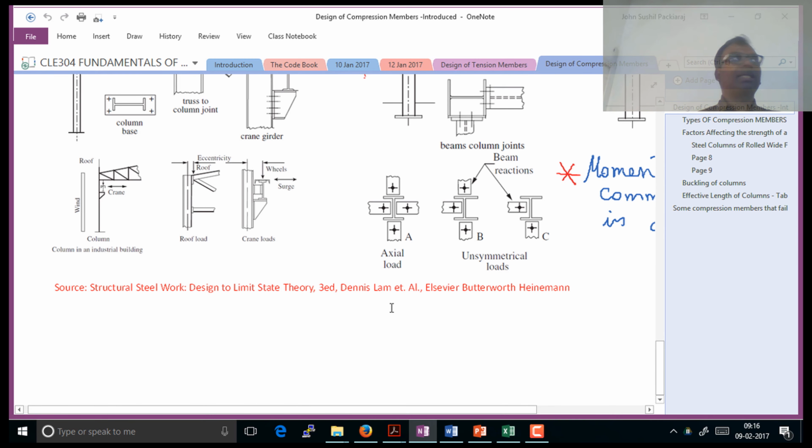If you take a typical building frame, you will have a combination of an interior column. Here this is an interior column which is predominantly axially loaded. If you have a column somewhere in the middle of the building, you got a cross beam which runs across the length like this one, and two beams which are having equal moments. The dead load moments on both of them are equal. They'll cancel out each other. So it means that predominantly this column has bending in only one axis. The moment is only there in one axis.